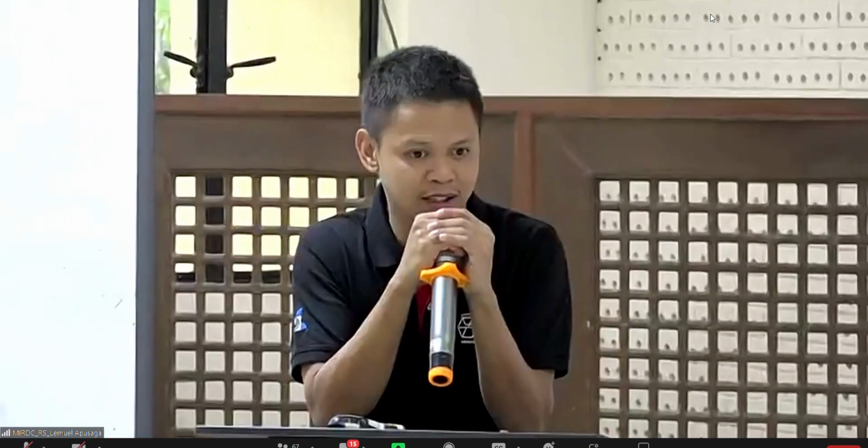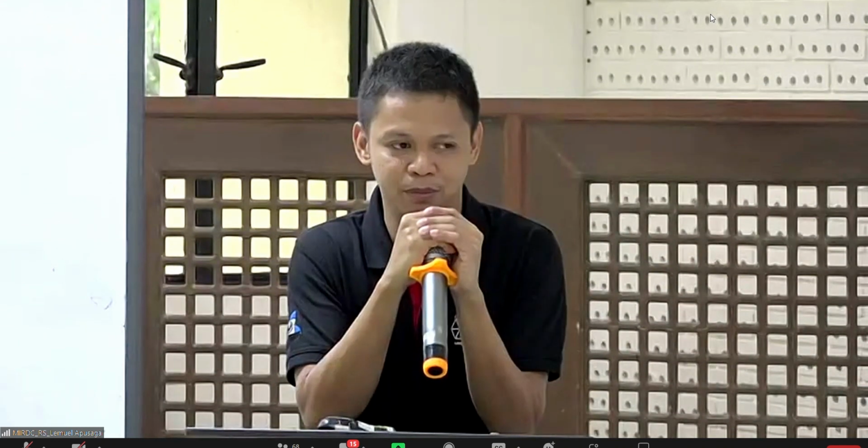Yeah, as I discussed earlier, you just have to select the appropriate infill percentage, because the only thing infill percentage affects is the strength of the casting. So if, for example, you're going to use it for the first 10 pieces, I think it's going to do good because you have designed it to withstand. So it depends on the volume of what you want to make. If you want to make a pattern for a part that has a larger volume, you design the infill density to be able to withstand that kind of volume.